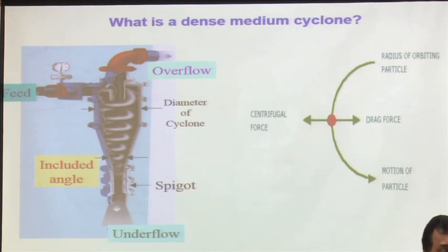Okay. So, force is more here and the cross-section area is less. So, there is a huge pressure drop from this region to this region, and this is open to the atmosphere. Because of this pressure drop, air automatically gets sucked from the atmosphere to bring it to equilibrium, that is called the inner vortex.